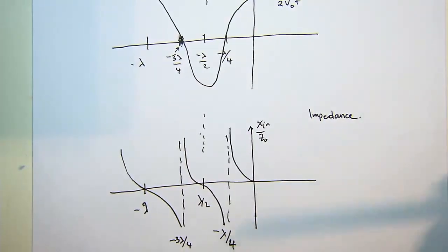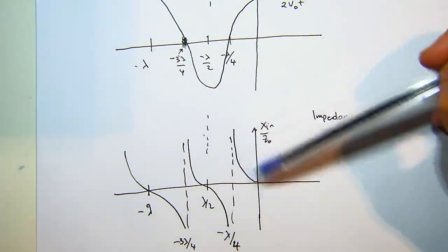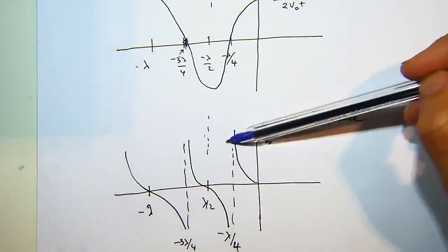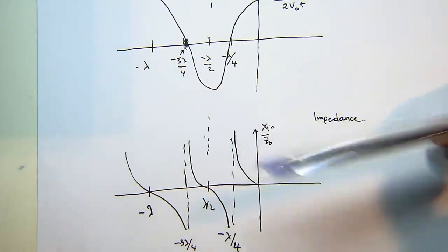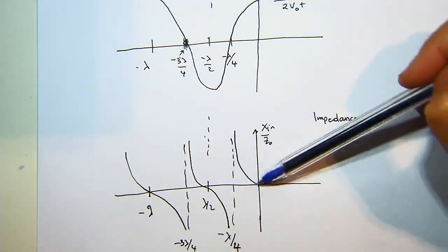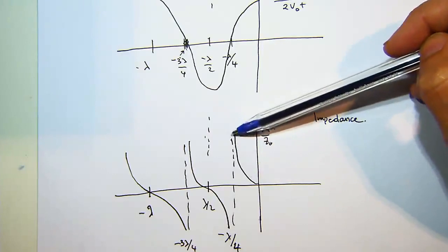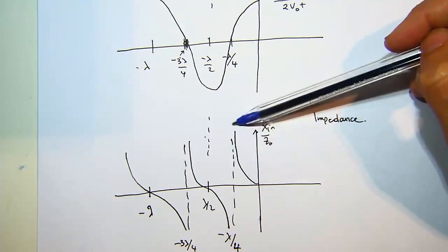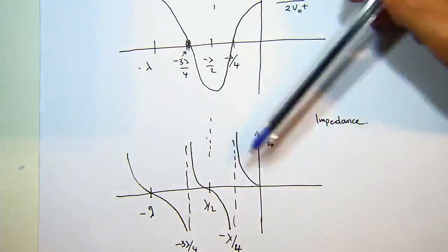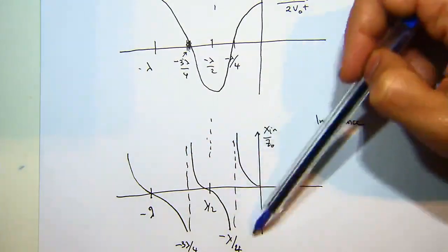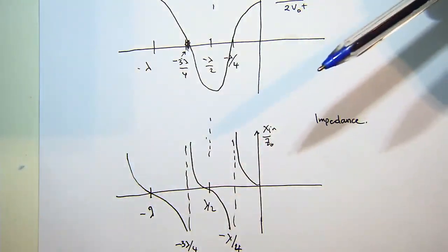And what was important was, again, just to re-emphasize that when you're going towards a quarter wavelength, you can actually transform a short circuit to an open circuit. Essentially what we're seeing here is, as the length of line approaches lambda on 4, we get infinite impedance, and this relationship is periodic. It essentially repeats itself every lambda on 2.